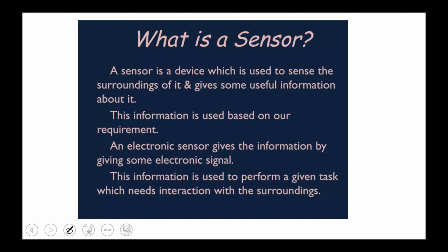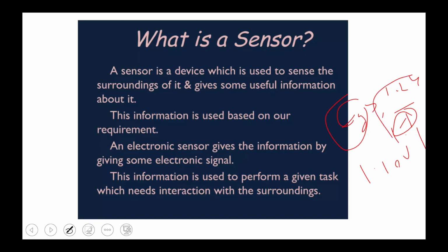Yes, so we use, for example, an IR sensor, infrared sensor. To make an IR sensor, you use either silicon or germanium. Those are the properties they detect, because if you read the formula, your band gap should be greater than or equal to 1.24 upon lambda. Lambda is the wavelength of light. Yes, sir. And the band gap of silicon is about 1.1 electron volt. Okay. So if you divide by 1.1, how much will the wavelength become?